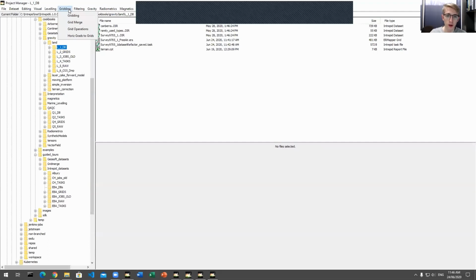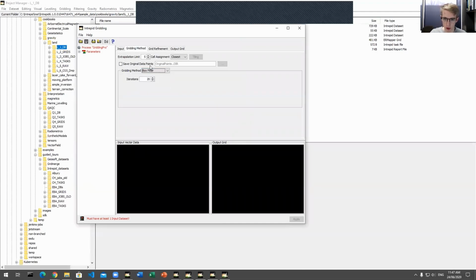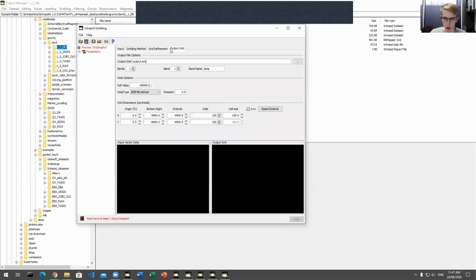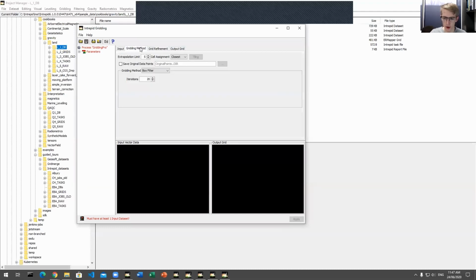Of the gridding techniques available in the gridding tool, I'm relatively confident all four of the gridding methods have the ability to honor the original data. The one that I would need to confirm on is variable density. But from what I know, with the artifacts and the pimpling that we see using variable density, they are honored. That is a primary cause for those. But to what extent, I'm not too sure.